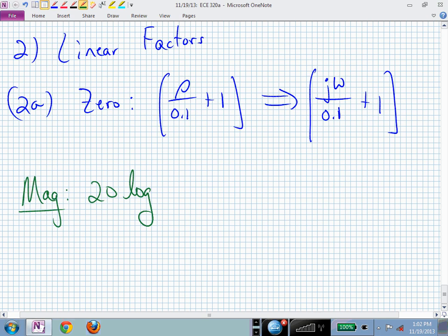The sweet spot being right at the pole or 0, right at the break. And small means what relative to the break frequency? 1/10 or a decade below. Large means big, or 10 times the break frequency, a decade beyond.